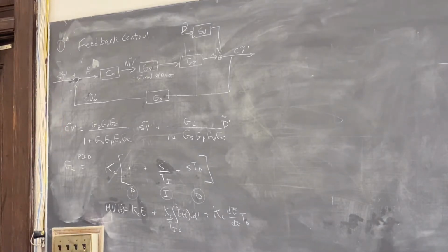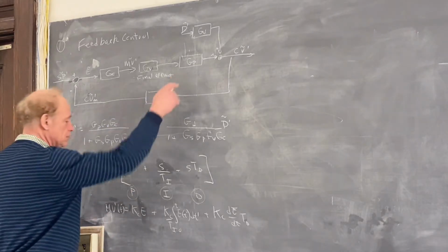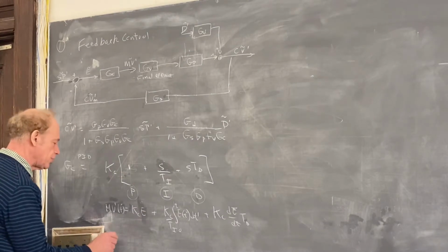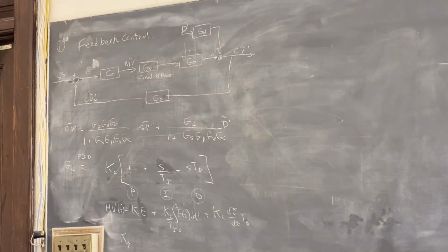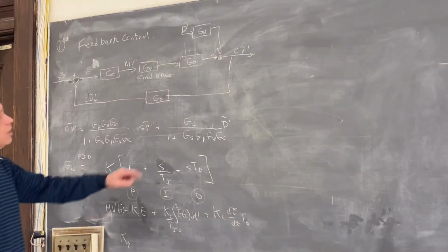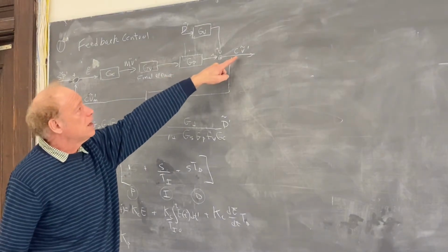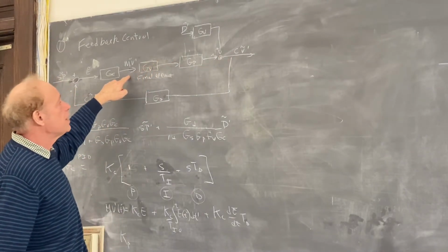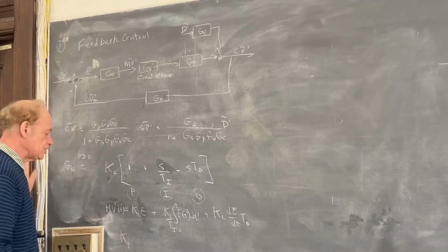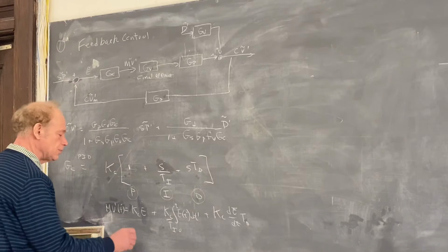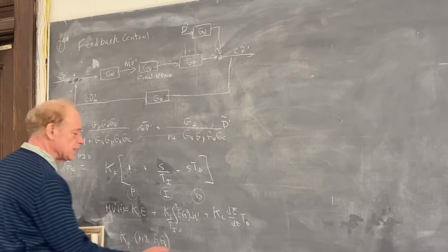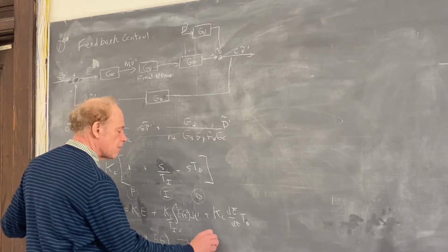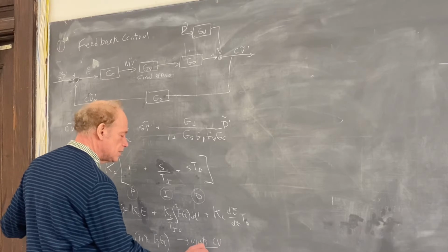Let's just notice some units here. The units of GP usually involves a KP. KP is inside the steady state gain. So notice the steady state gain has units of a control variable over a manipulated variable, or GP GV. So KP comes into GP GV, and it has units of the control variable over the units of the manipulated variable.